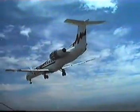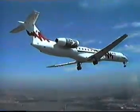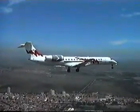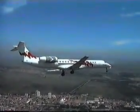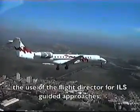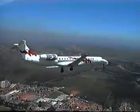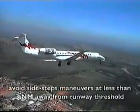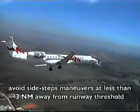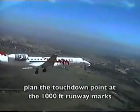For a normal glide path of 2.5 to 3 degrees, the resulting rate of descent is about 650 to 800 feet per minute. Rates of descent in excess of 1,000 feet per minute should be avoided. The use of the flight director for ILS guided approaches and VASIS and PAPI for visual reference is recommended. If possible, avoid sidestep maneuvers at less than 3 nautical miles away from runway threshold. Plan the touchdown point at the 1,000-foot runway marker.